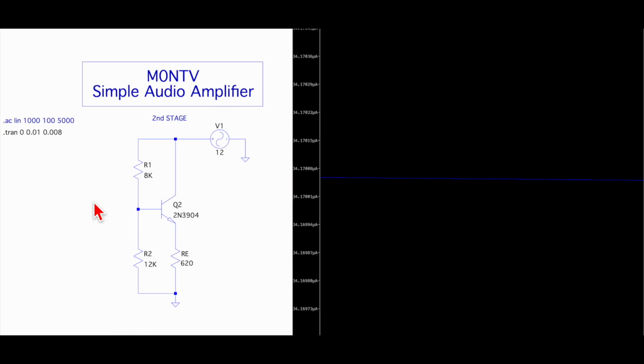It will give you no voltage amplification at all. In fact, you'll get a slight loss, but it will give you plenty of current. So it is a useful little amplifier. So all our voltage gain will come in the preceding stage, and then this will just beef up the current so that we can drive our loudspeaker. Now, it's a simpler design because there's only 3 resistors, and we'll AC couple the input when we get to it next time on the base here, and we'll AC couple the output on the emitter.